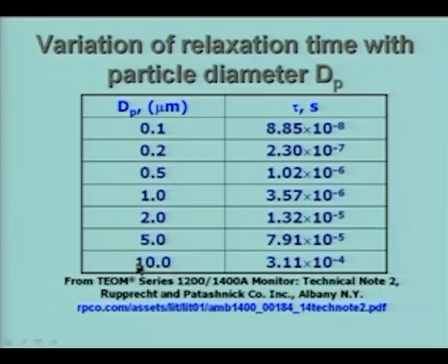These are very large particles and these are relatively smaller particles, and this is the kind of particle we talked about when we were talking about the diesel engine. So, you see that the relaxation time is very small, about 10 nanoseconds here, and then progressively here it is about 1/10 of a millisecond. For very large particles, this relaxation time has something to do with isokinetic sampling. We require that Stokes parameter to be less than 0.01, and this relaxation time goes into that formula.